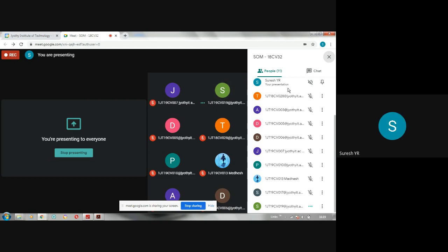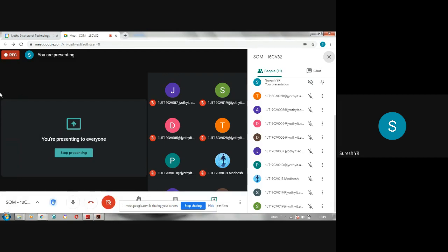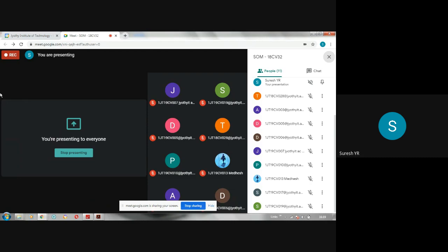Next, for the maximum deflection, put that value of x1 as 2.5 in equation 4. Substitute it in the deflection equation, equation 4, and whatever deflection you get, that is your maximum deflection. Y max is 1 by EI into 2 into x cube, that is 2.5 cube, minus 5 by 3 into x minus 2, that is 0.5, 0.5 cube.